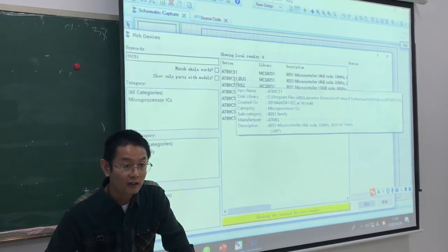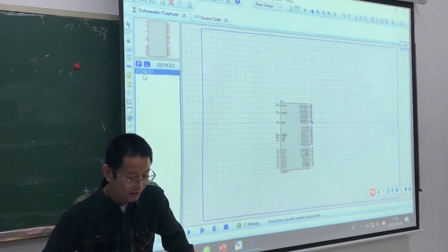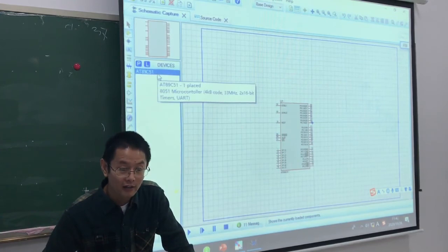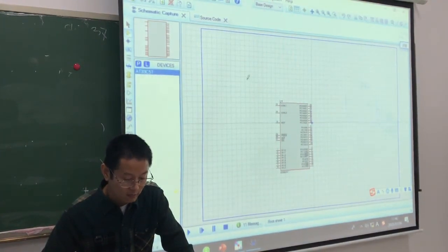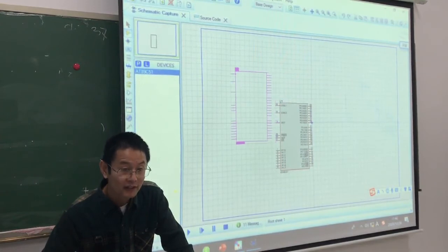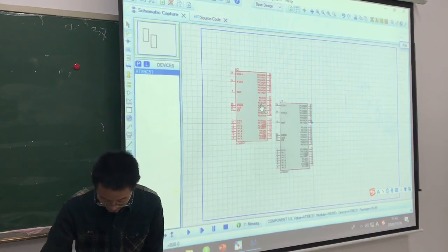Double click. Then the AT89C51 is added here. So click and put it here. I already put one. Delete.